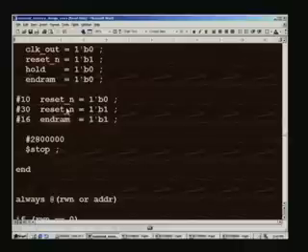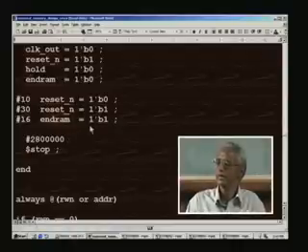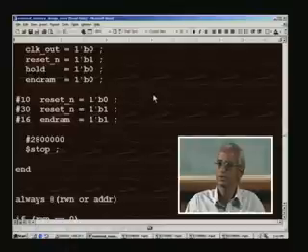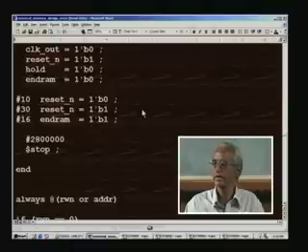What we have to do is just terminate the whole process after a delay, and note that a huge delay is required, so many clock pulses, because we are treating 64,000 locations, and each, as we have seen, takes 2 clock cycles for either a read or write, and we have write as well as read to be performed. That means 2 plus 2, into 2, and 64,000.